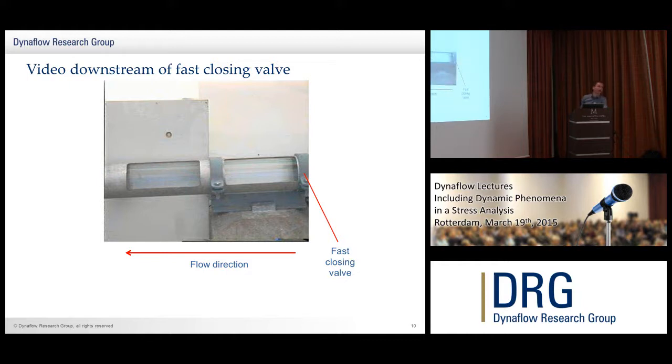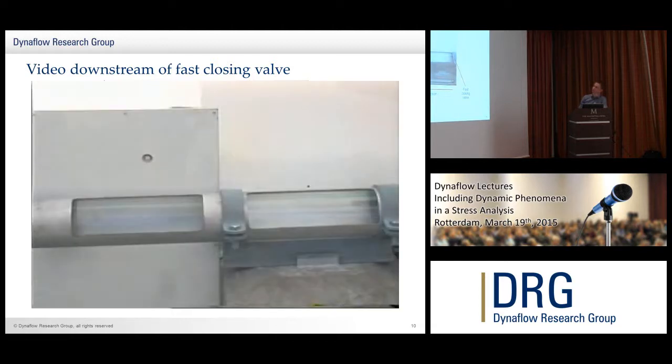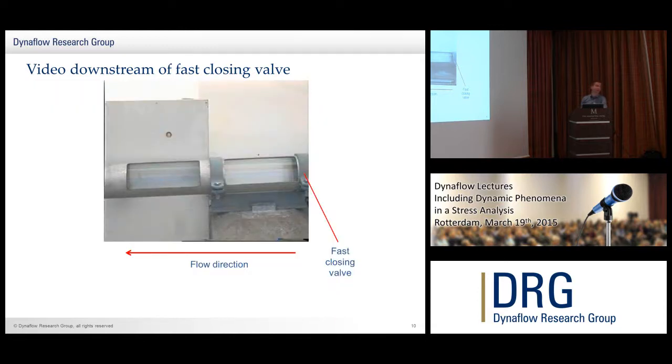So what we saw there shows an example of the sort of force and the dynamic pressures that actually occur. You see the flow move away, you see the void forming, then the pressure recovers because of the lower pressure in the void, and the flow moves back towards the valve, and then ricochets, moving away again. That is an example of pressure surge downstream of the closing valve.